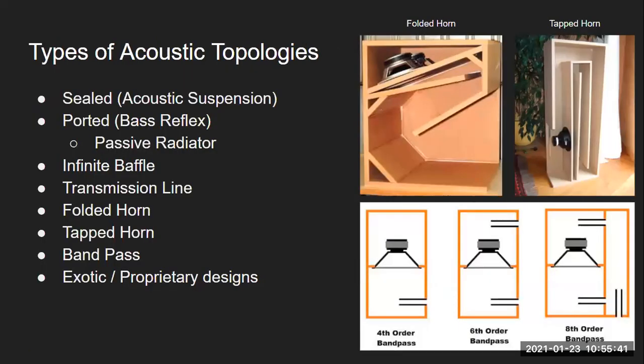So here are some examples of some acoustic topologies. I'm going to go through the first 4 in a little more depth, and I've got some pictures of the other ones as well. But you can use all different types of acoustic topologies to augment what the speaker driver itself would play on its own. Some of the most common ones are the sealed and ported designs. That's what 95% of the designs you see are. And then there are some more fun ones.